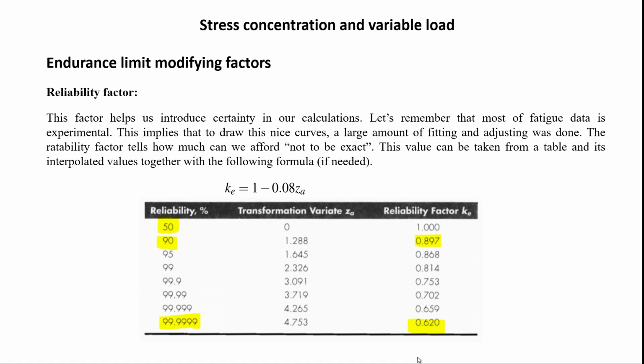So that's why design against fatigue results in larger pieces, larger designs, or engineers trying to avoid high loads, high load variation, or a large number of cycles. But when that's impossible, then you're going to end up with oversized machine elements, oversized designs. So that's why.